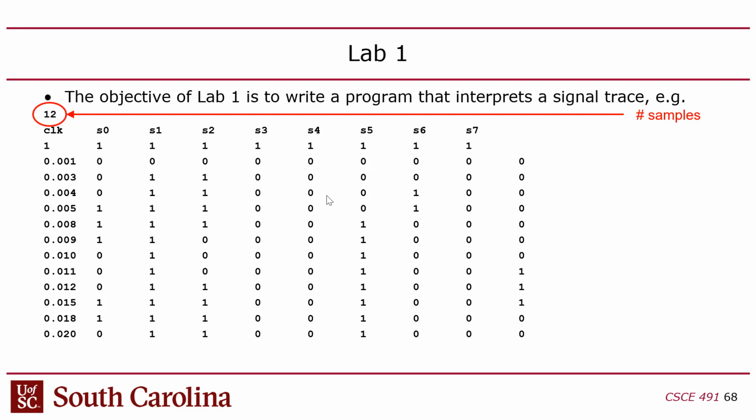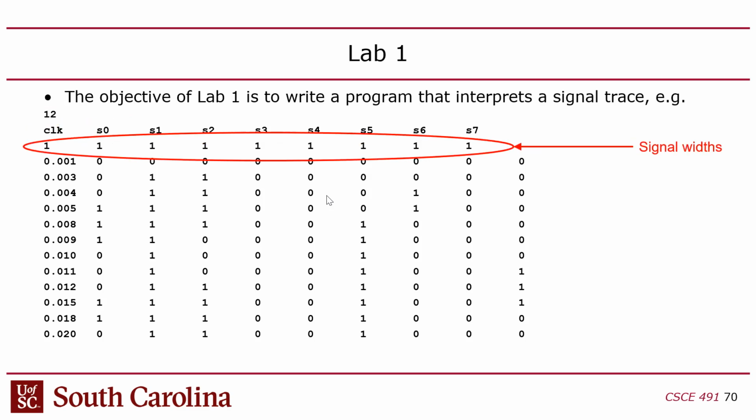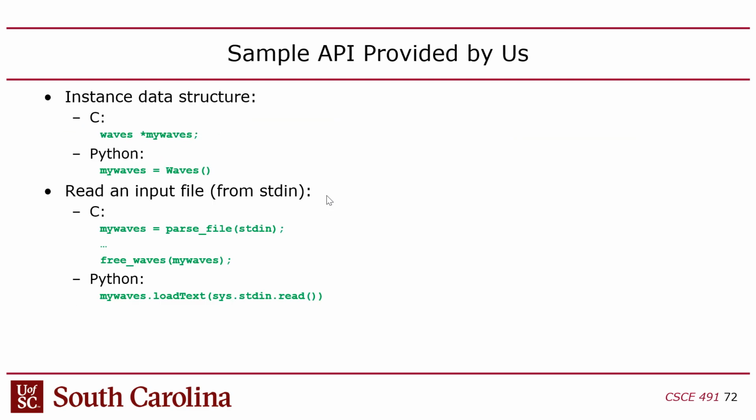So as a result, these things are shifted over to the left a little bit, which makes it a little hard to read. The next column is the number of bits in each one of those signals. Obviously, with SPI, they're all 1-bit signals. We've done other versions of this where we looked at other protocols that had more than 1 bit, but we don't use those anymore. And then every line is just time, followed by the state of each signal at that time, right?